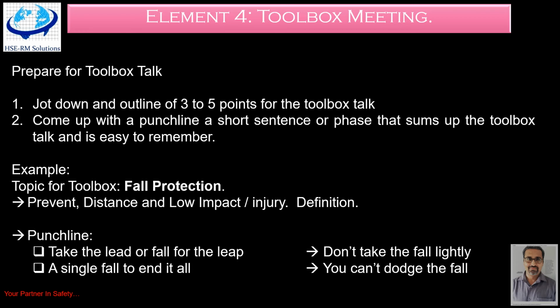Then you have the full body harness that you are wearing. If you have anchored it at a proper place, you will not fall. Then you can tell them what the preferable areas are where you are ideally supposed to anchor yourself, and why you are supposed to anchor there. Whenever you're talking of fall protection, the very first aspect is that you must anchor yourself in a location which is a robust supporting structure.